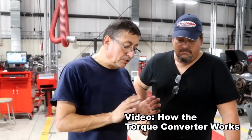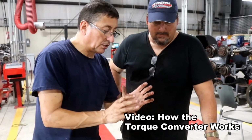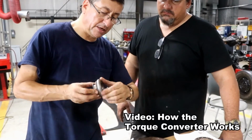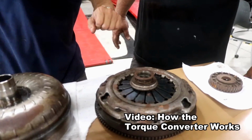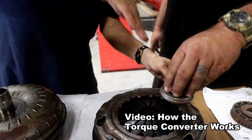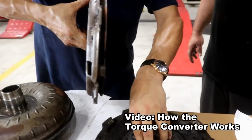Nice. In order to easily understand the hydraulic clutch, we need to finish with the mechanical clutch. The thrust bearing, this is an axial bearing, is moved by the fork, and the fork by your pedal. When you press, this metal goes here, and the friction is free.